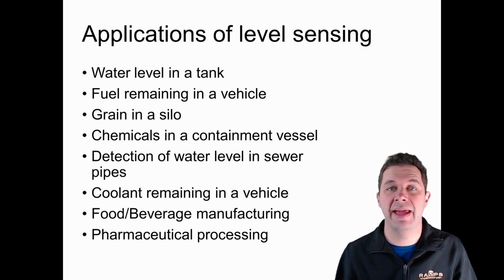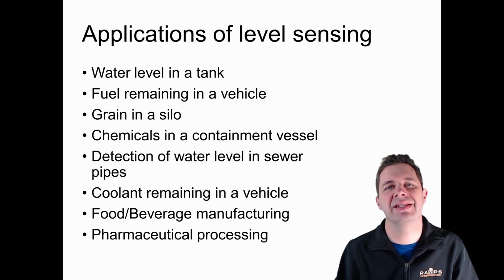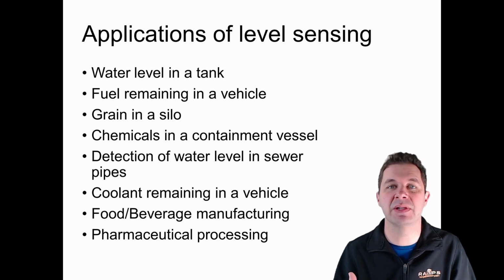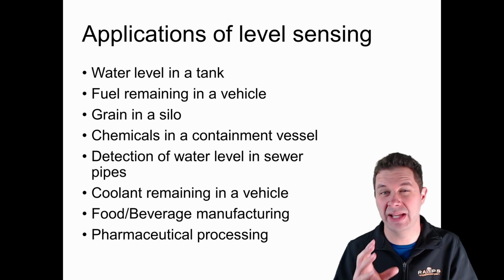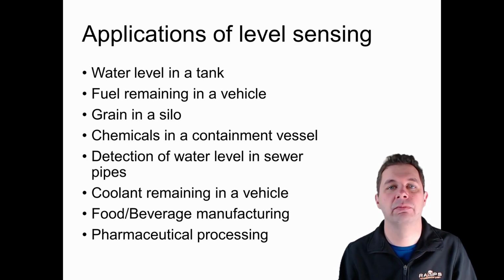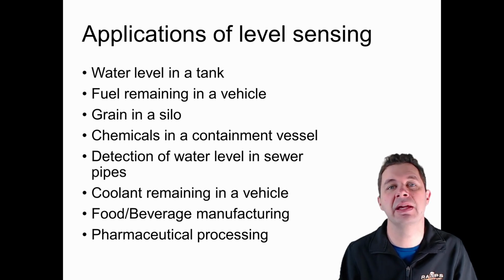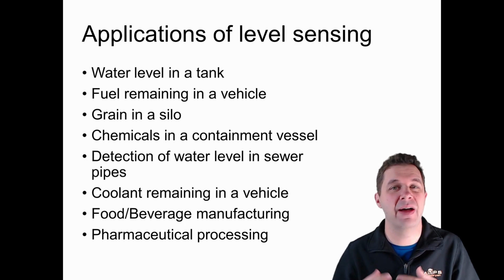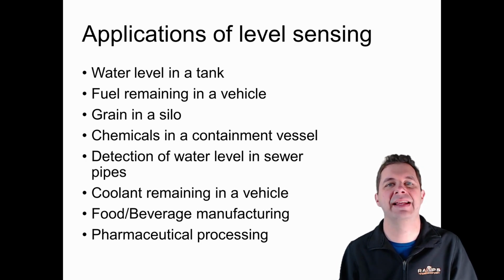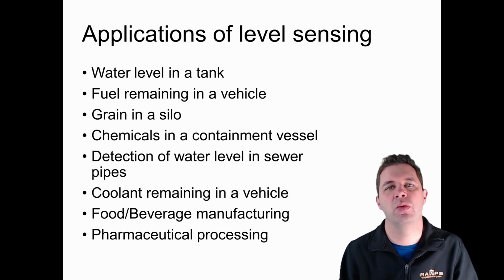or sometimes these level sensors are used within sewers to look at, in high rainfall events, what level of sewage comes up within those sewers and how much they increase there. And they can be used to set alarms for there might be part of the sewer that's blocked and starting to back up, and we can start identifying where that is with these level sensors. We might be sensing level as in our coolant levels in our vehicle or something, or also we might be using them in beverage and food manufacturing, pharmaceutical manufacturing, and many other related areas where we're trying to build things and we need to know how much of a particular chemical we have available.